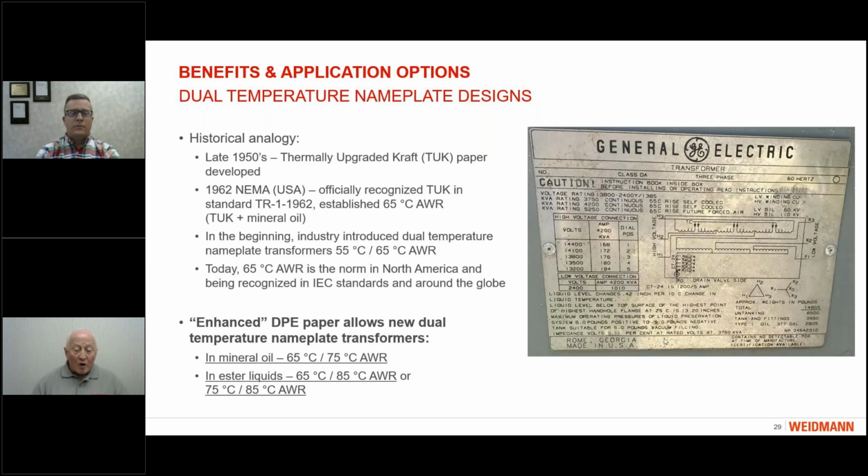So again, to draw the analogy with what we are discussing today with enhanced TPE paper, we can say that it's possible to design dual rating or dual temperature transformers with 65/75 Celsius in mineral oil, and 65/85 or 75/85 average winding rise in ester liquids. Next, please.